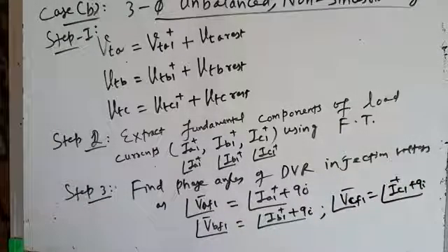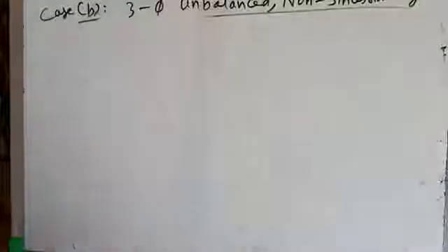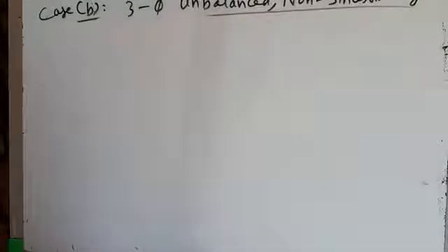This is step 3. Step 4, you have to do the same. You have two equations with you, equation A or equation B. Now if you have information about feeder impedance, you can use type 1 control, hence equation A. And if you don't have information about feeder impedance, you can use type 2 control, that is equation B.